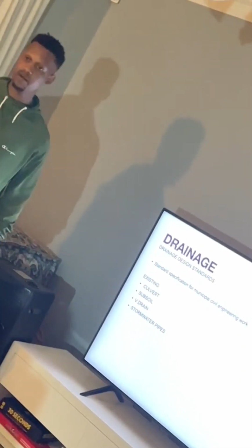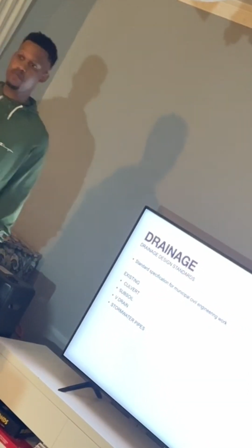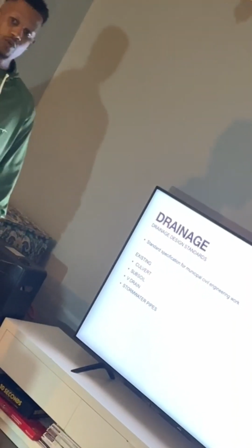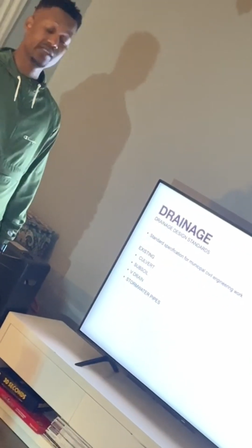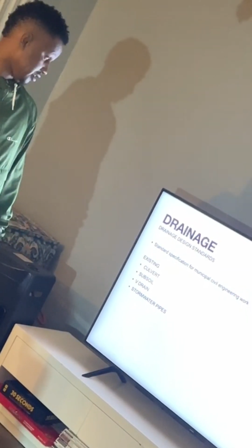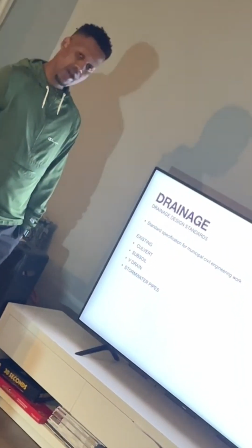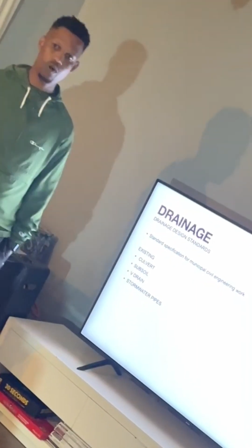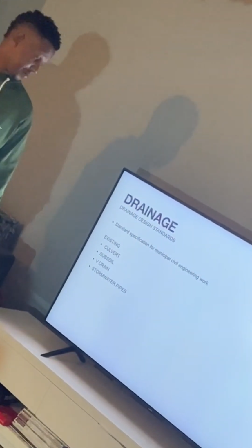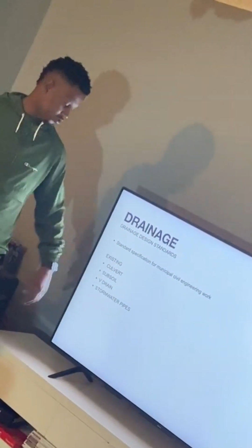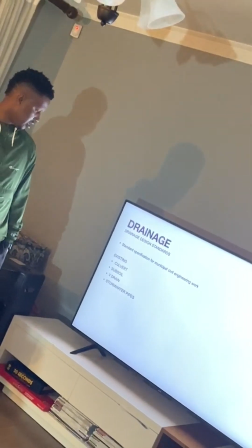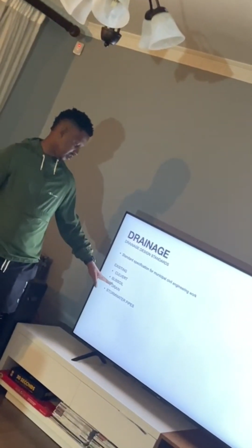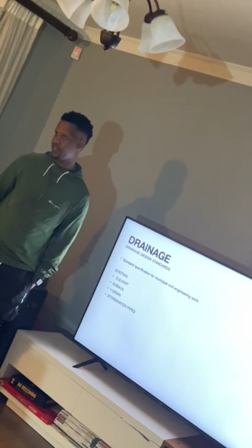There are existing V-drains on the road. The only challenge is that they have been damaged, and as such, it is our opinion that they will not perform and drain all the surface water away from the road as required. So we are going to reconstruct the V-drains from chainage 1 to chainage 1.24. The 300mm stormwater pipe will be upgraded to a 750mm diameter pipe, which is going to cross under the road at chainage 1, and that is exactly where the V-drain is going to be daylighting, and we'll also have the subsoil drain running under that V-drain.